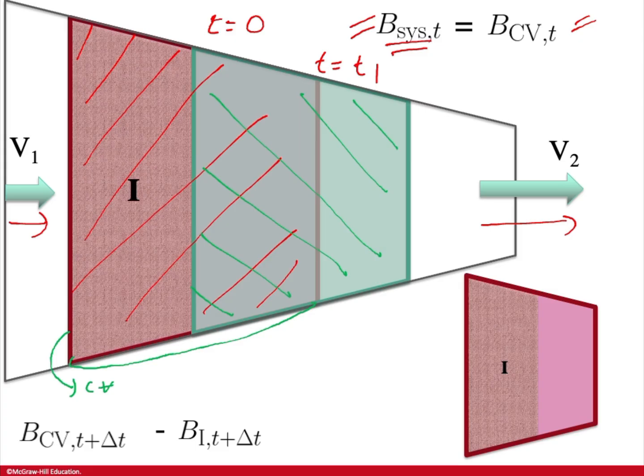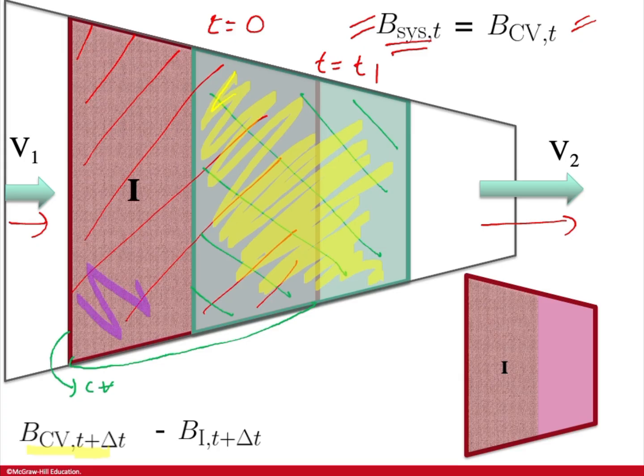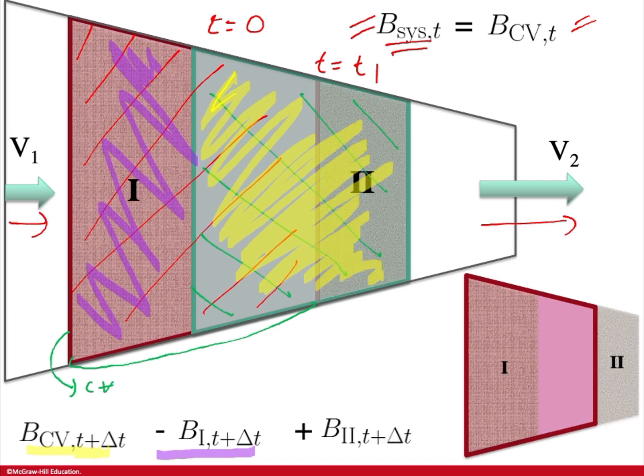If all you want to do is get an expression for this green volume from things that you know, essentially, if you knew the initial control volume, that is the red part, you subtract this volume that is given by 1 from the red, by this expression right here, and then add this volume 2 that is new there.